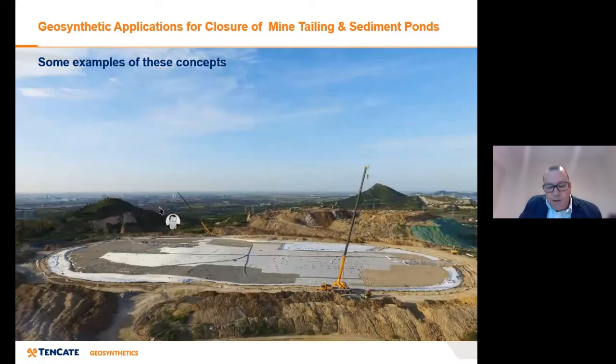And an aerial shot of a project in China where all the panels are laid out. You can see some ballasting probably for uplift. That's all buried in around the edges for anchoring trenches, and then progressively moving out with the material so that you're progressively tensioning, putting the reinforcement into action. And in this case, they're working from the side, but there's also some equipment moving slowly out, pushing the materials around.